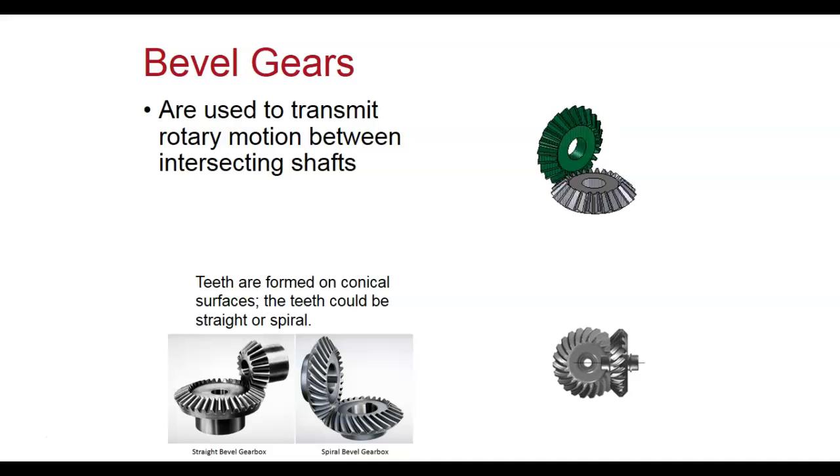I was looking at that one. We have a little one here and a big one here, so you calculate depending on which one's the driven and which one's the drive. This one is hard to tell. To me, it looks like this is a little smaller than this one. If they're the same size, though, it's just to change the direction. That's a good point.